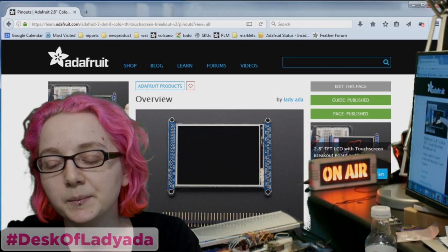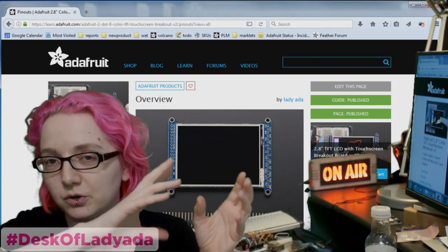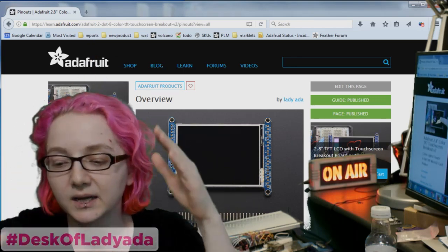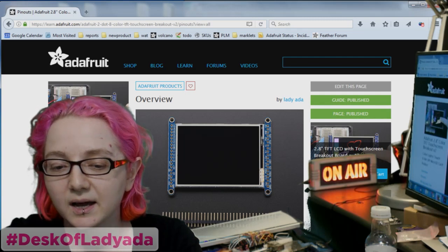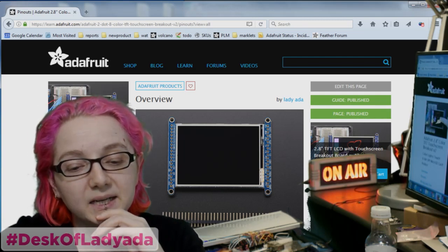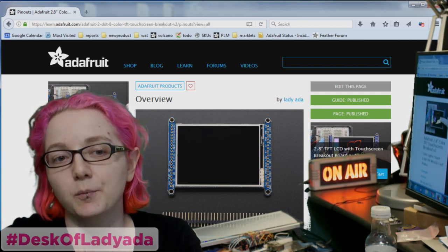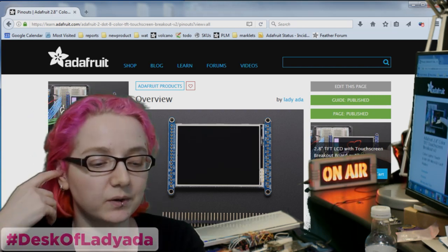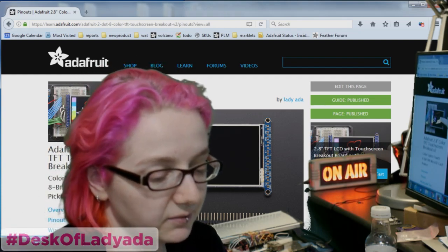And it's a little bit more complicated as a technique. As you've seen, we had to show how you have to pulse and measure, and you see the change, and it's very susceptible to noise and fluctuation. The resistive touch is actually a lot easier to use. It's easier to implement as an engineer, but it's more annoying for people. So I'll just show some resistive touch on the overhead so people can tell the difference. And this is how you can tell whether your device has resistive or capacitive touch.